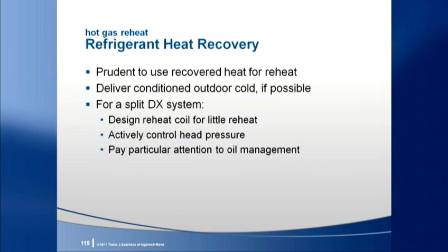The challenge is in the design of the heat recovery system so that it operates reliably when the system is likely under the simultaneous abnormal operating pressures of hot gas bypass. One consideration may be to minimize the reheat coil capacity and deliver the air as cold as possible. Another is to actively control head pressure. Remember, in a split system, to pay particular attention to oil management. Oil does great things in the compressor, but does little good anywhere else.